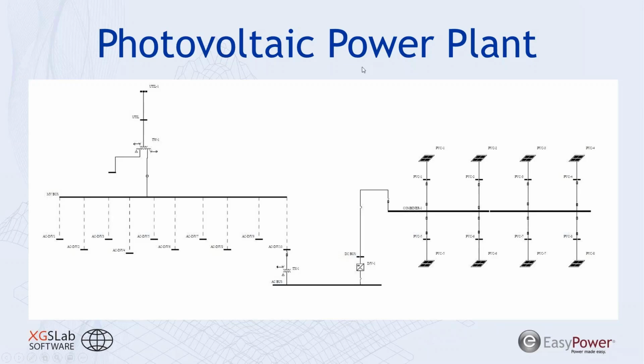We have our PV panels on the right, and these are connected at the inverter and then converted into AC power, and that AC power is often stepped up to a medium voltage. That medium voltage could be transferred back to the grid at an existing utility station, or often with these larger 50, 100 megawatt solar power plants, they could have their own collector substation. And that substation could convert that medium voltage into a high voltage for transmission back to the grid.